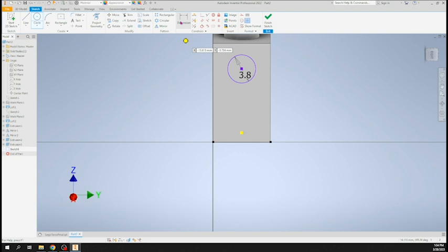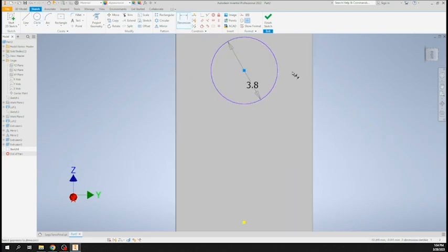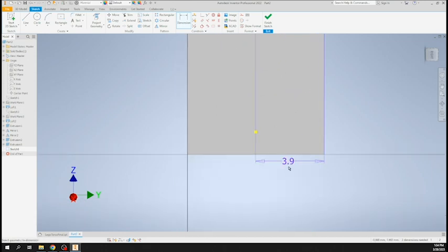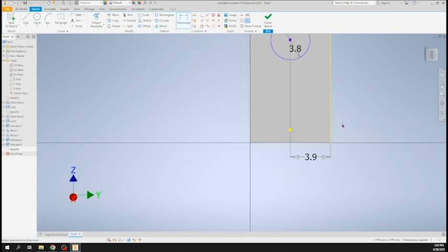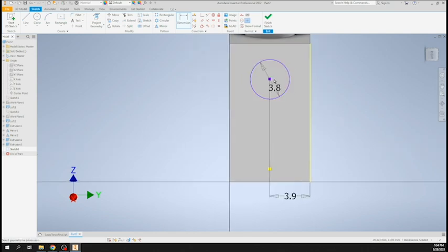All right, let's take a couple measurements. Okay, so use that dimension tool again. We're going to start at the center of the circle and go to the edge. Okay, and what is that dimension? Mine says 3.9, and that's exactly what it should be. Somehow got that just right, so make sure it's 3.9. And then we're going to take another measurement, okay? And this one's going to be from the bottom. We'll click on the center and then hit the bottom here. And this one should be 9.2. So I went a little too high there. I'm going to change that to 9.2.